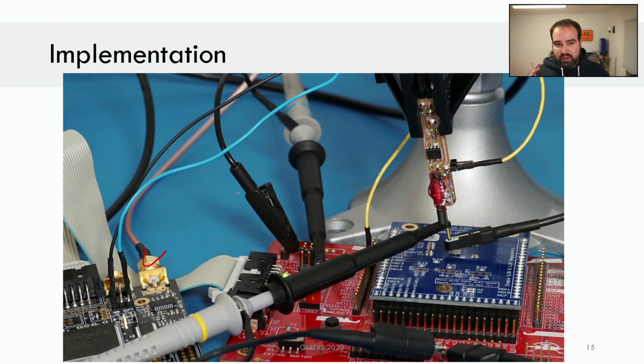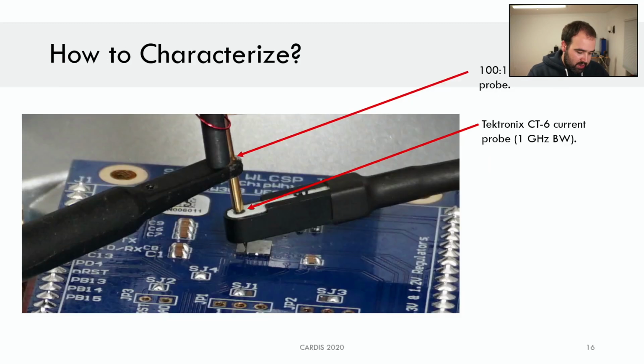You don't need $1,000 worth of equipment to make this $10 probe actually possible. You just need a power supply, right? I'm using a bench lab power supply. You could use a really cheap LM317, anything like that. And you need a way to generate the glitch. So those are the only real hard requirements.